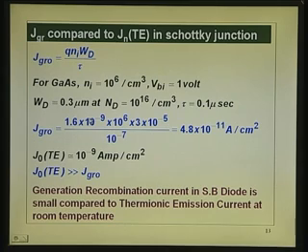Very easily, 1.43 is the band gap. So, a 1 volt built-in potential you can easily get. All that you have to ensure is, you do not say that the built-in potential is more than the band gap. If you say silicon has a built-in potential of 1.2 volts, then that is not correct. So, it is always less than the band gap. W_d for doping of about 10 to the power 16 is about 0.3 microns, a rough number.